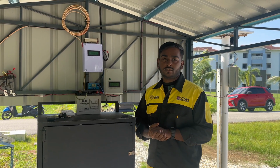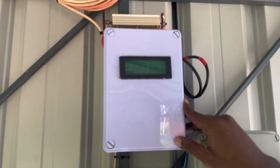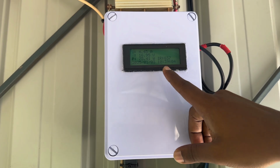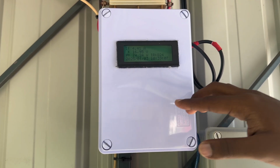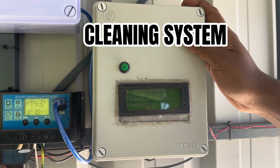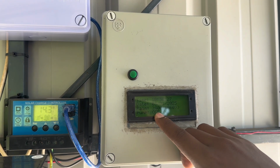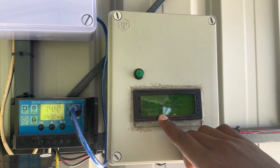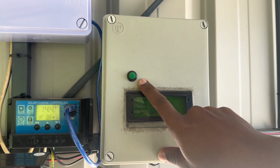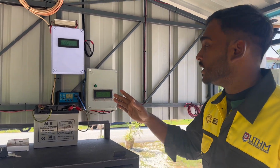Today I'm really excited to demonstrate my project. My project consists of a data logger. This data logger reads current value, voltage, Pmax and irradiance, so we collect the data on a real-time basis. Beside it we have the main unit for the cleaning system. This system works on a schedule basis, every 7 a.m. in the morning. Here we can see the real-time data and the pump activation mode, which is on and off. We also have a button for manual activation to test. This system is powered by this battery, which is connected with this solar panel.